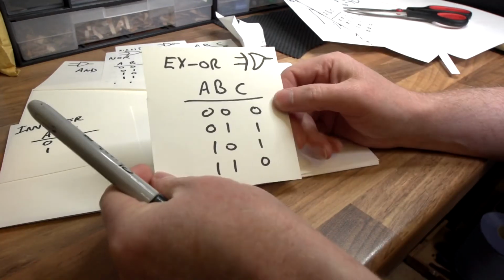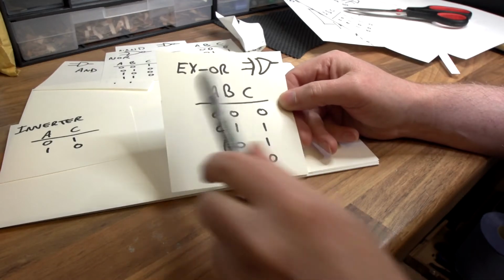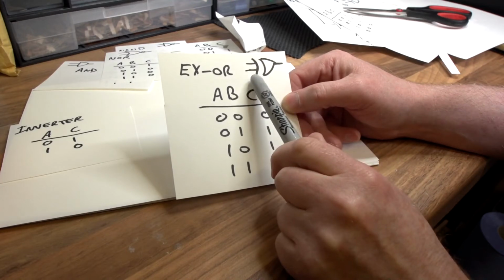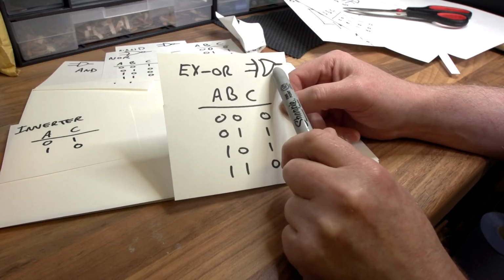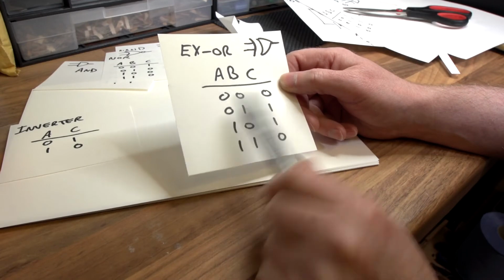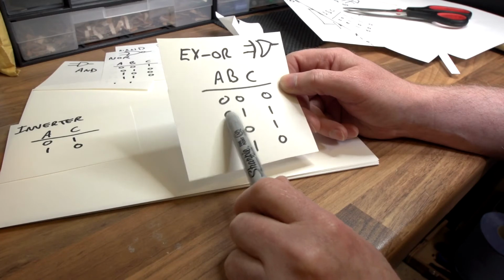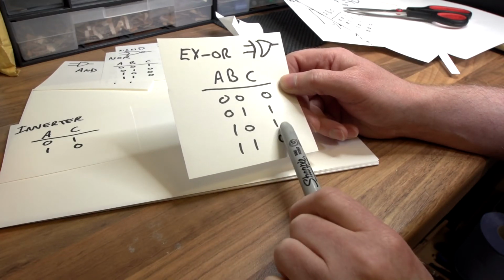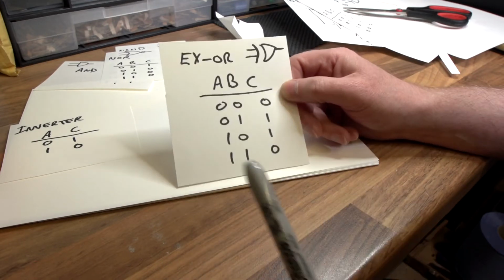Then we have the weird one. It's not really weird, it's actually very useful. The exclusive OR, or the EXOR, as it's sometimes reduced to. And that's the symbol here with its curved line on the input and a curved gate front end as well with the 2 input pins. The EXOR is basically a difference detector. 0, 0 would give you a 0 because they're the same. And 1, 1 would also give you a 0 because they're the same. So only when there's a difference, 0 and 1, well that's a difference, that gives you 1. And 1, 0, they're different, so that gives you a 1. So whenever there's a change of the input, when they're not equal, then you get a 1 output. So that's an exclusive OR.